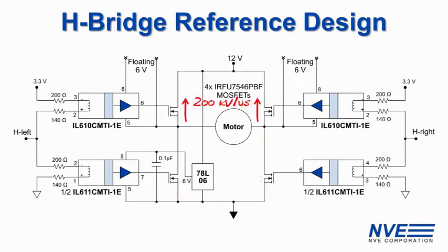As the high side MOSFETs switch, the isolator power supply and ground change rapidly. This rapid change in voltage can cause current flow across stray capacitance proportional to dV/dt, which causes the isolator to glitch. So common mode transient immunity, or CMTI, is a key figure of merit for H-bridge isolators. Fortunately, these particular isolators have very little stray capacitance, and the devices are symmetrical and well matched, so stray currents tend to cancel.